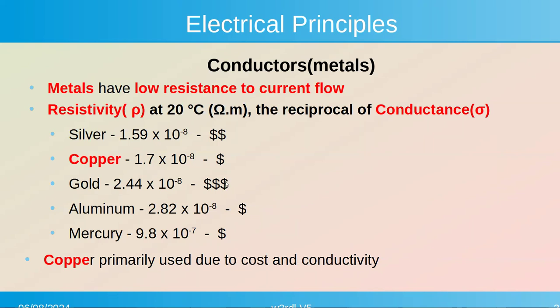And we don't use it except, like I said, on plating conductors or connectors, things like that, where you care about oxidation. Because both copper and silver oxidize, where gold won't, so it'll handle the environment much better. There has to be a barrier between gold and copper, because they're not compatible. So when they gold plate contacts to protect them, you electroplate a thin layer of silver first, and then you electroplate gold over the top of that. Because you need that barrier between them.